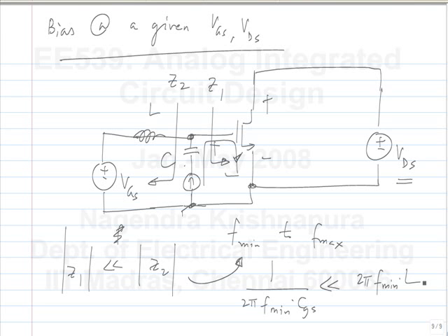What about C? What is feeding the capacitor is the current source, right? So I don't care if there is an extra drop here. This current will go through the capacitor, isn't it? Whatever the value of capacitance is. If I have some voltage source here or something with a non-infinite input impedance, then I should make sure that all of the current goes here. But in this case, what happens if I put a smaller capacitor or a larger capacitor? Only this voltage will change. Okay. The voltage between this point and this will be I divided by C1 parallel C2. So actually the capacitance value doesn't matter.